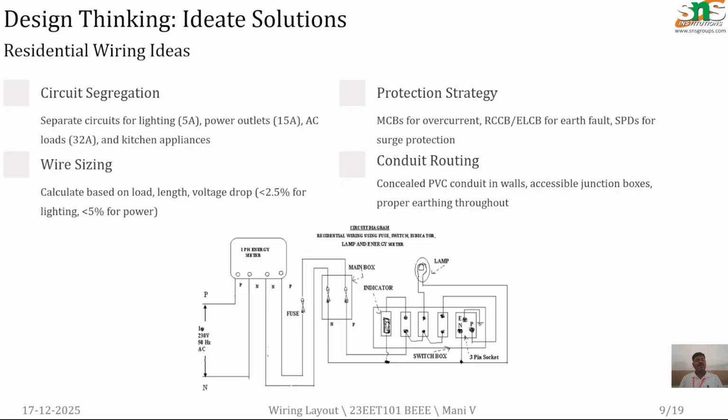Based on the load calculations and the loads, we have to choose the wiring size. It may be 1 square mm, 2.5 square mm, 3 square mm, like that. And if you go for a light load, 1 square mm is enough.